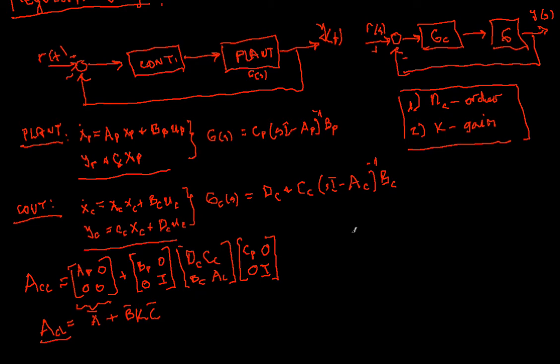So these are two parameters that we can use in order to explore and to ensure that the regulator stabilizes the system. Okay, and what do we have if we just think about a simple gain-based controller? Because we can use just a simple constant gain as a first option. So if K is just gain, no dynamics, and the order of the controller is equal to 0, the controller does not have dynamics. We get just the following picture: R of s, plus some gain K, G of s.